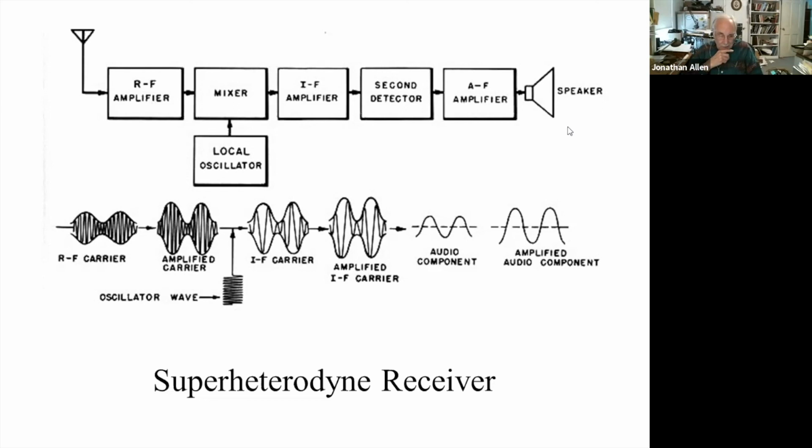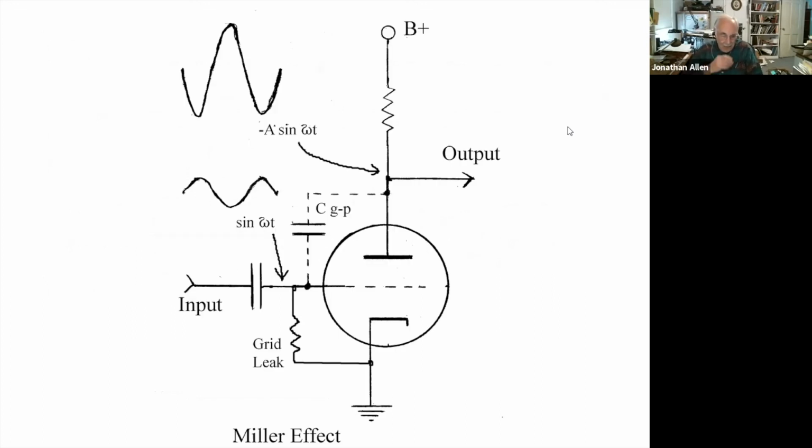We saw in the regenerative circuit that in-phase feedback can raise the gain of a triode, but negative feedback can suppress the gain. An unintended source of negative feedback is due to grid plate capacitance. As already mentioned, early triodes began to suffer serious loss of gain at a few hundred kilohertz. And by the time you reached a megahertz, the gain was approaching unity. So it was hardly amplifying at all.